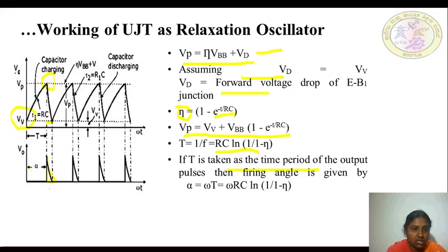This charging time period can be considered as alpha. So the firing angle is omega into T, which is equal to omega into RC ln of 1 divided by 1 minus eta.